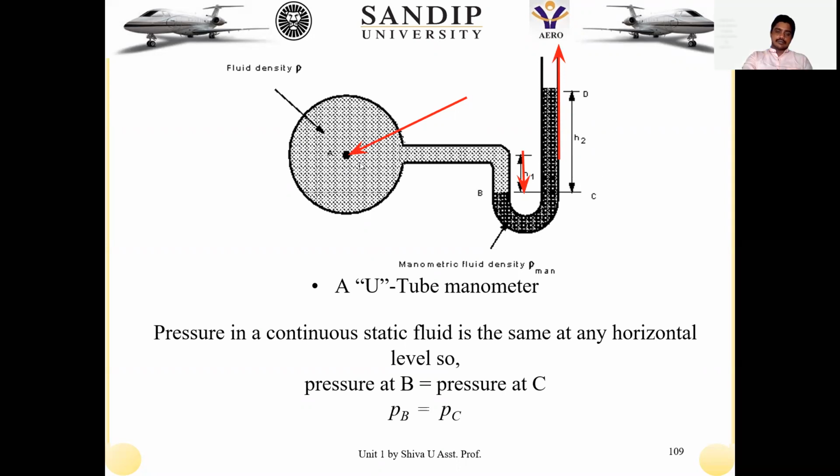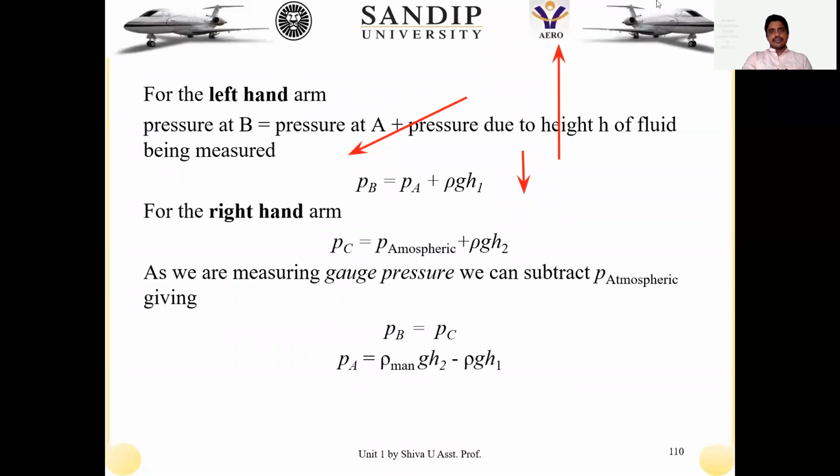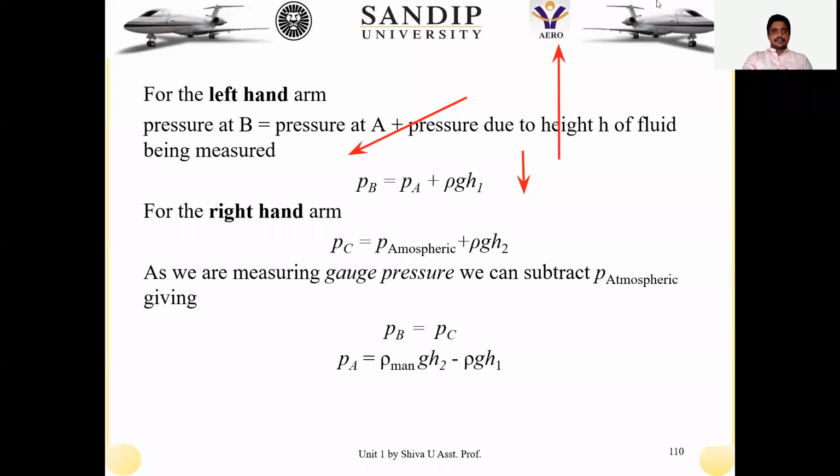We have to change the liquid, because at the point A and at the point C, as shown in the representation, the liquid is varied. So I have to write it as rho A here, and here rho C, for the fluid available in this U-tube. Let us write it as rho 2 G, where G is the gravitational constant which is fixed, and H2, rho G H2.